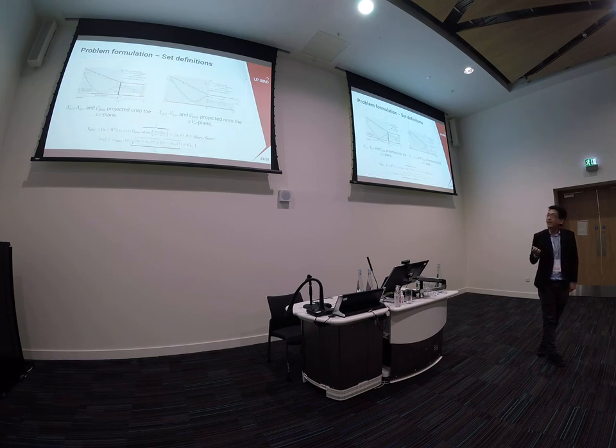Now we see again these two figures. So the state constraint for the MPC is what we call the line of sight corridor. No matter what happens, the state has to stay inside the red corridor. So the white trajectory here is the reference trajectory, and the blue is the MPC trajectory. You see that at the end here, we have a dot and dash trajectory. This is the predicted final trajectory of the MPC.